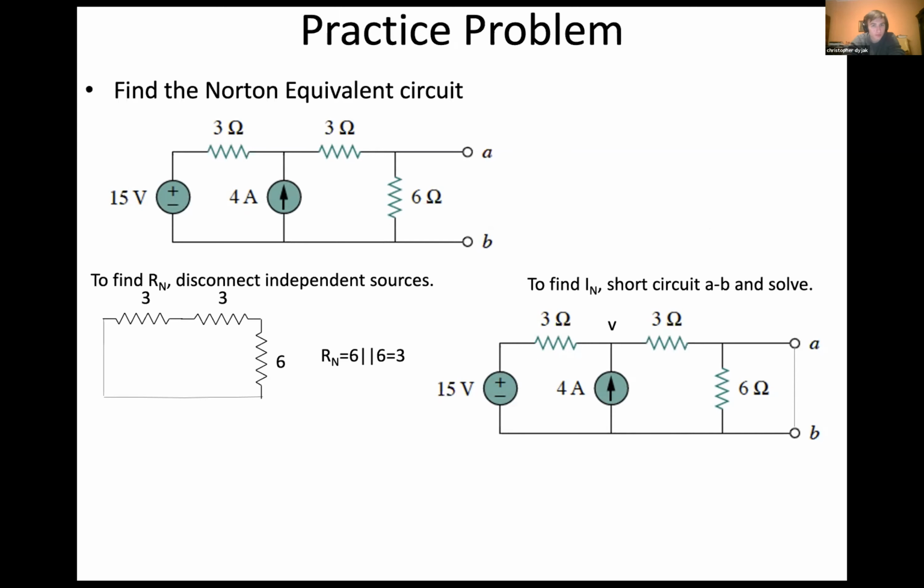It should be 5 amps, right? Nope, you don't know that yet, because this is not ground. It would be 5 amps only if V was equal to 0. So this current here is (15 minus V) divided by 3. Yeah, Christian, that's right. Put the parentheses around the 15 minus V. How much current is flowing from here to here? Yes, very good. V over 3, excellent.